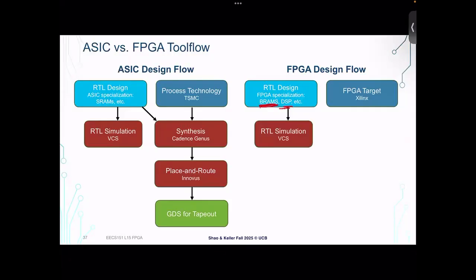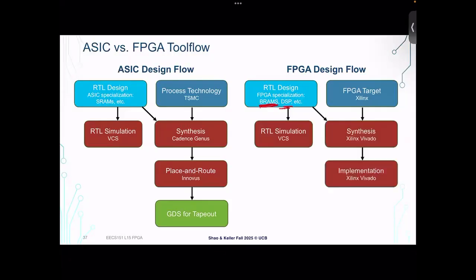RTL simulation looks pretty much the same. You still can use VCS or a commercial tool, but the synthesis and implementation, instead of place and route, we call it implementation, are different. One key difference is that they're generally using a vendor-provided tool rather than a third-party EDA tool from something like Cadence. Another difference is that instead of synthesizing into gates, it's figuring out how to program all the LUTs and all the switch boxes and so forth.